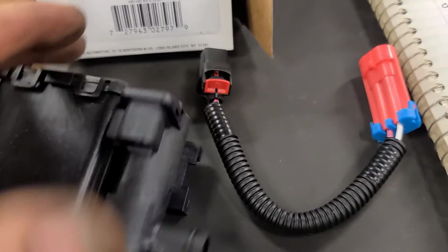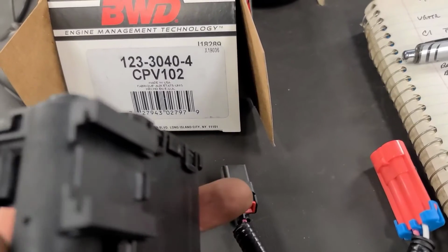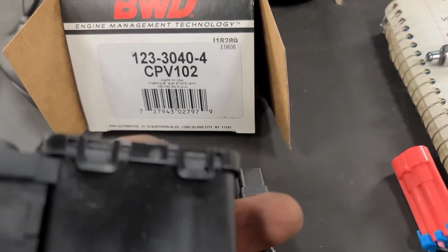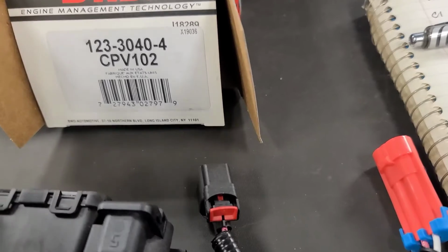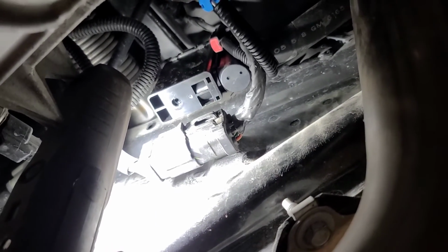So this one comes with the change-up harness, and it's held in with a little clip. Usually we just break the old one, taking it off, and then slide the new one on. So there's the new solenoid installed. You remove the one hose clamp and slide the hose off the back. Obviously the electrical connector is unplugged, and it slides off the bracket towards the back of the car and then slides back onto the bracket until it stops. I unclipped this from the body and then reattached it after. Put the little jumper harness in because it changes the style of the connector.